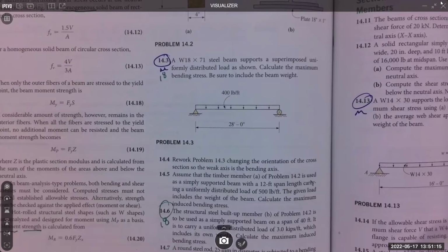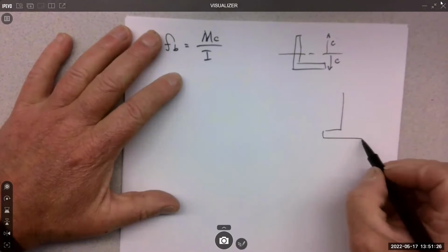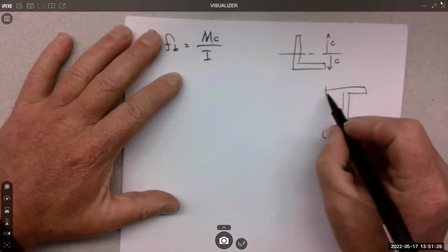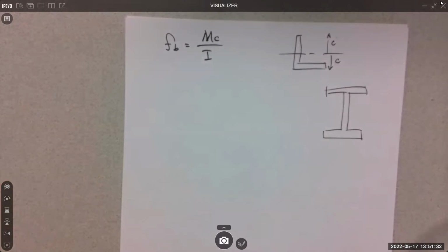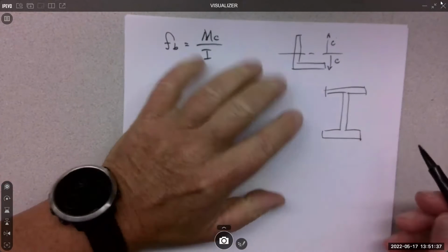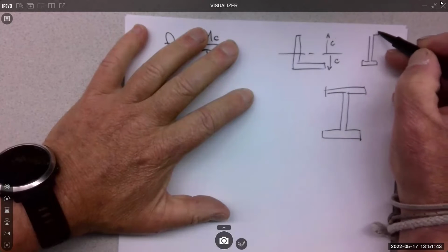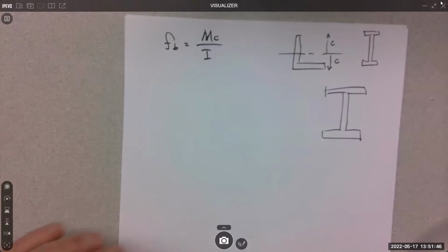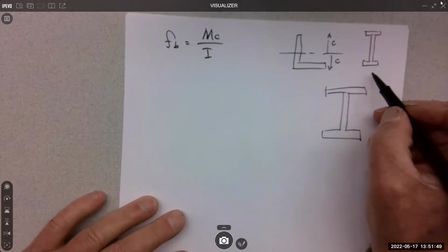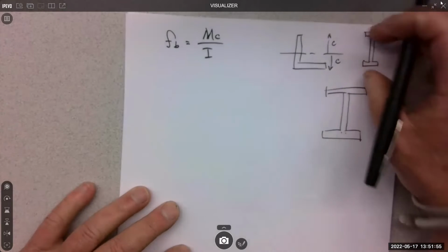Height. Yeah. So a W shape is what common folk call an I-beam. They're not I-beams, they're W-beams because they have a wide flange. That's where the W comes from. The flange is wide. True I-beams, and there are I-beams out there, look more like this in perspective, where the flange is very narrow. I-beam, W shape, much wider, same height kind of thing.